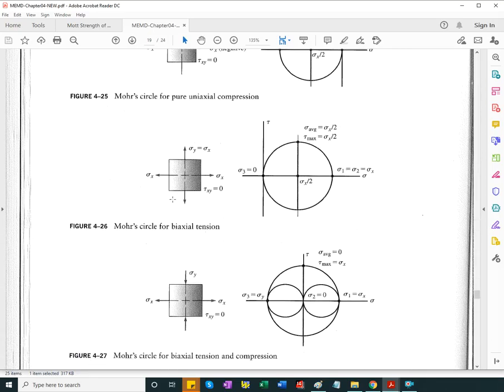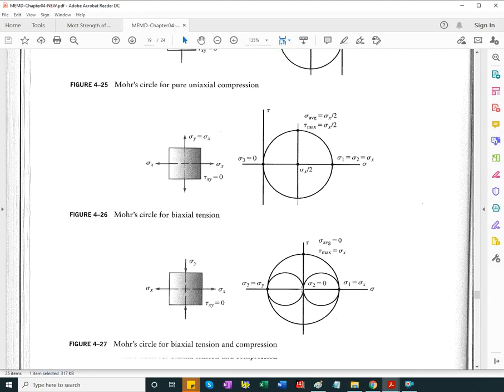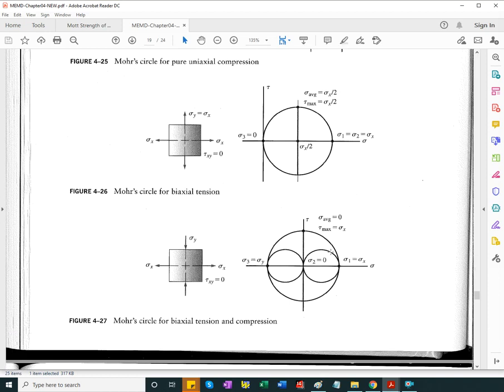Biaxial tension comes to mind. Again, in the pressure vessels, there was longitudinal and hoop stress. Hoop stress, for pressurized pipes and cylinders, is twice the longitudinal stress. And here's where I said the 3D circle is useful to be drawn.